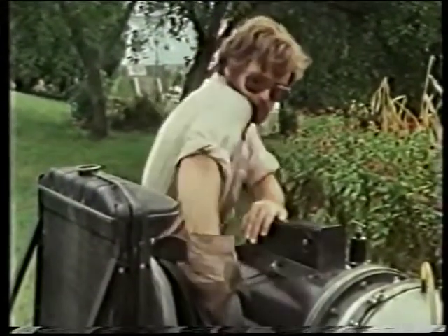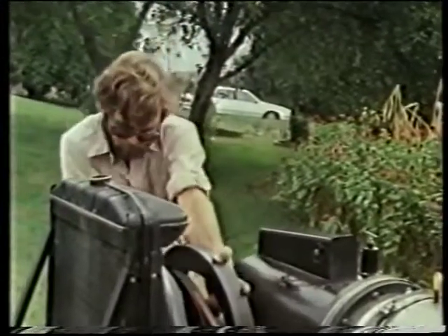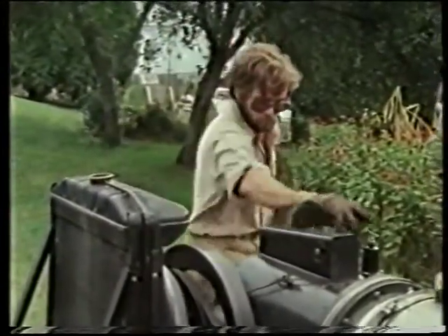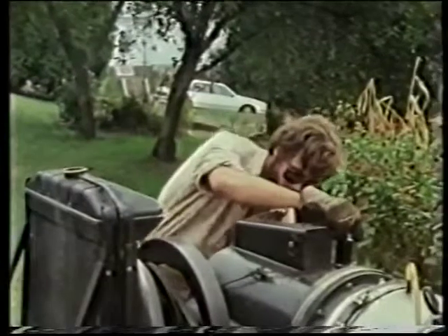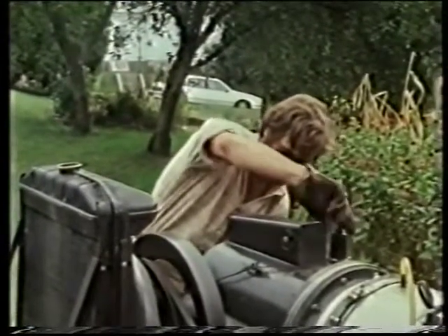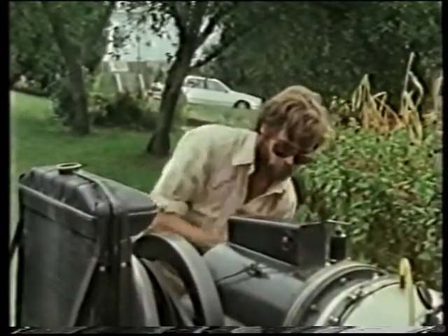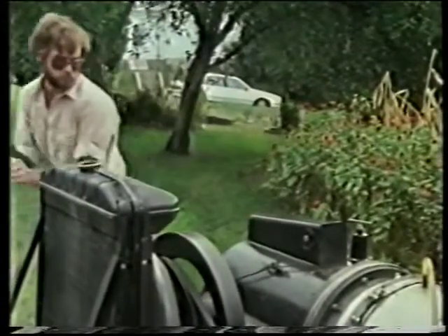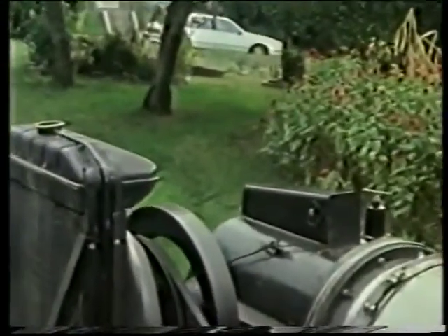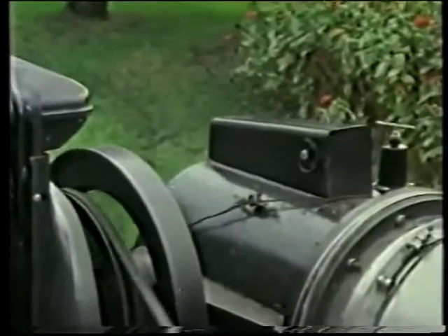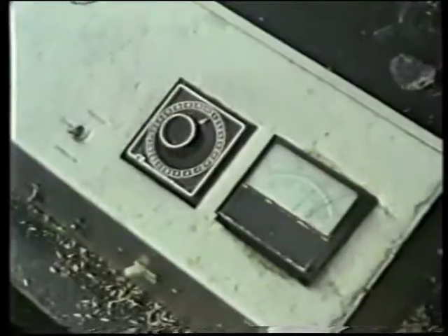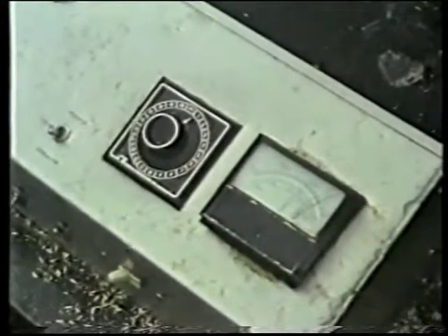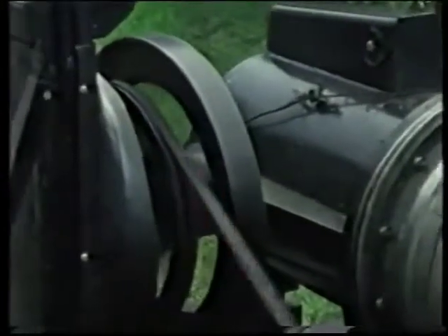It works on the same principle as the standard Stirling cycle. That is to say, it has an external source of heat, which is used to heat air. There's a piston inside which moves the air back and forth between the hot space and the cold space on the engine. It has a cooling jacket just like a normal engine. And as the pressure rises and falls, it pushes the crank piston back and forth, and that generates mechanical work.